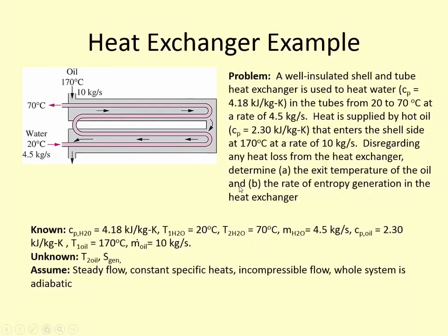All right, fixed. Okay, so this is just what we've done before. Now, we want to find the rate of entropy generation in the heat exchanger. So if we want to look at it as a whole, we need to think about how we define our system and be careful, right? So if we look at the rate of entropy generation for the fluid stream, let's say we're looking at the rate of entropy generation for the water.